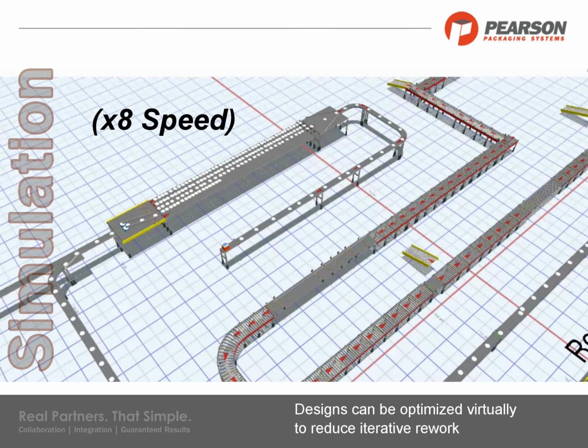The 4th lane is now filling up. This gives us a lot of time to be able to service a piece of equipment if it's down. So as that process restarts downstream, we can discharge this accumulator and continue to keep the product flowing both upstream and downstream while holding a large quantity here in the middle.